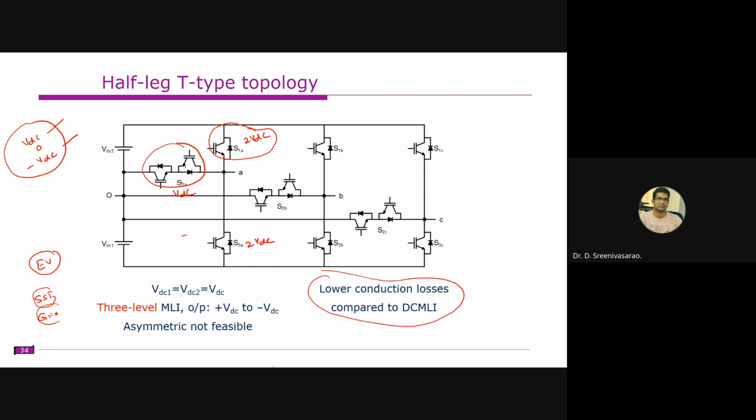So that's why this is very popular, especially in the EV drivetrain and electric vehicle chargers. Chargers of 350 kilowatt or 250 kilowatt are available for high power charging. Most of the high power chargers prefer this T-type converter. So we have the dual active bridge DC-DC converter, and on one side, this is usually based on the T-type converters.